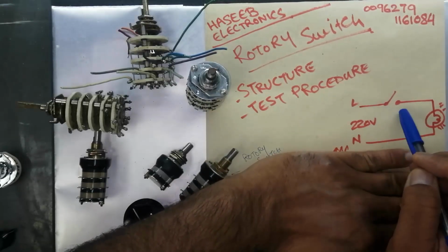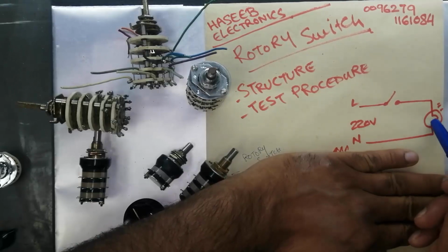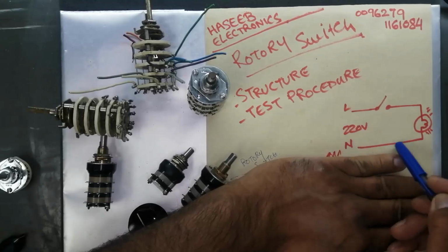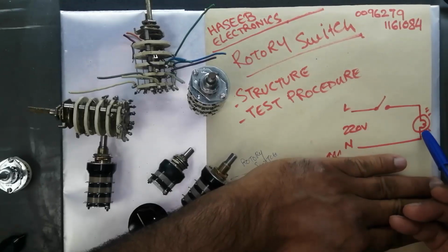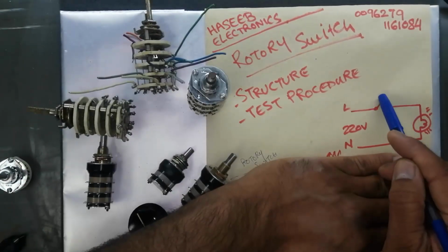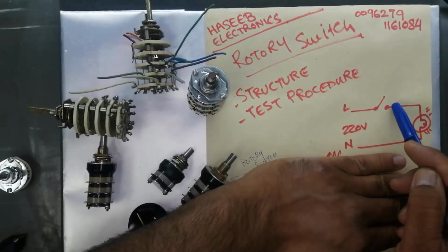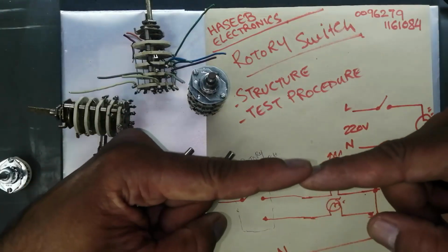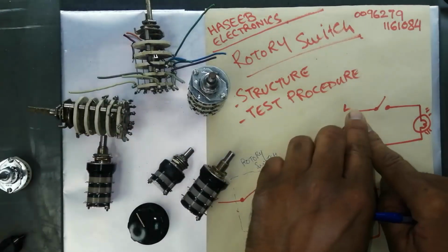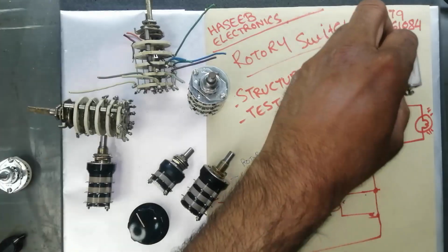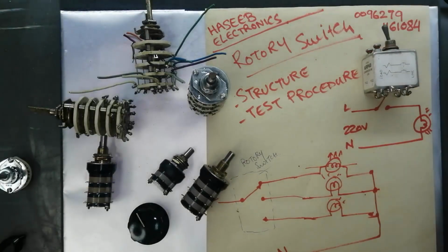When we use a normal electrical circuit, we use a lamp. In our home electrical wiring, there is line and neutral. The neutral line is connected to one side of the lamp. From the other end of the lamp, a switch is connected. It is a mechanical device which is used to connect or disconnect two lines. Here is the line voltage, 220 volt or 115 volt, 110 volts. The switch is connected in between these two lines.